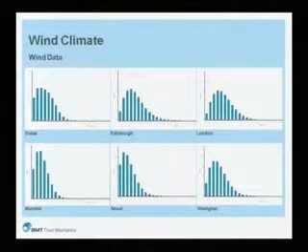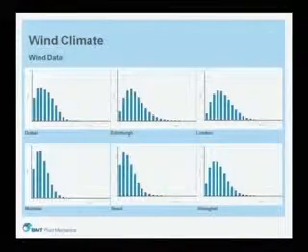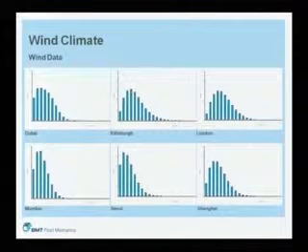They're shown in the form of what we call wind frequency data, and these plots show the probability of wind speed bands against certain wind speed ranges, and clearly there's a big difference depending on where in the world you're planning to put the wind turbine. So something that works in London doesn't necessarily work as attractively in Mumbai because the wind climate is different.